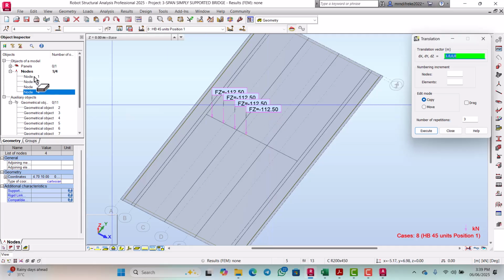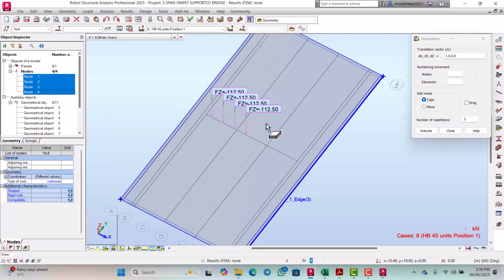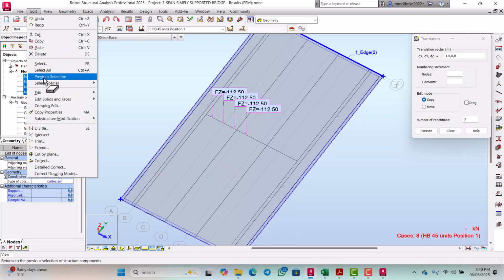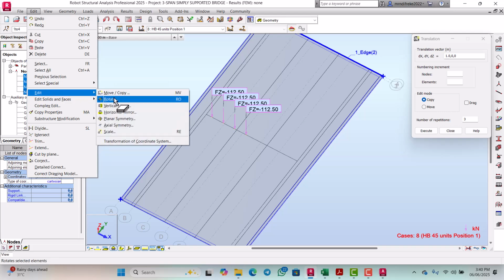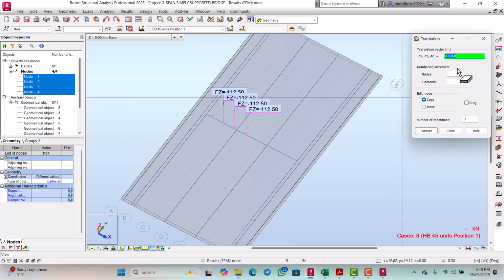So I will go back, click on this, highlight everything. Then I'm moving it on the negative y-axis. So I will come to this, click on, come to x is 0, negative 3, comma 0.